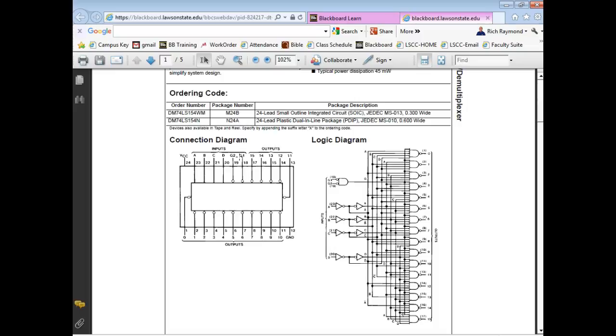Good, go ahead. We got our outputs. Normally we put the pin numbers on. You'll just run out of room, but we've got these hooked up too, right? We need the pin-out on the inverters. The inverters come in here, the inputs for the 74LS147, and they come down here and you put the outputs. The outputs would be the ABCD outputs. Don't worry about connecting up this one down here. So I'm on the right track? Yes, you're on exactly the right track.